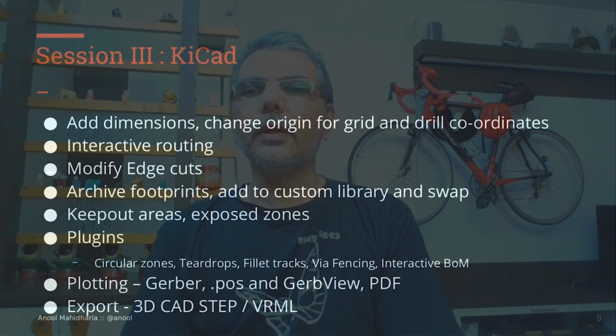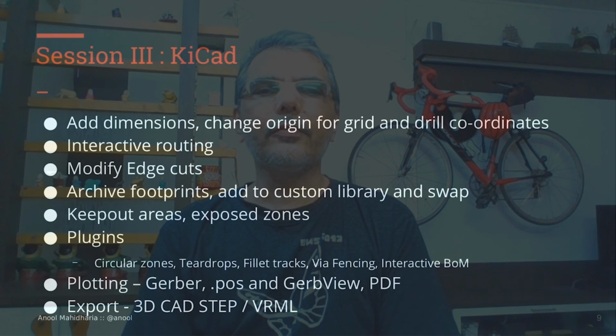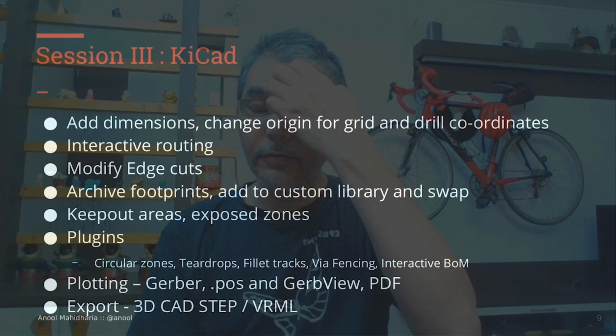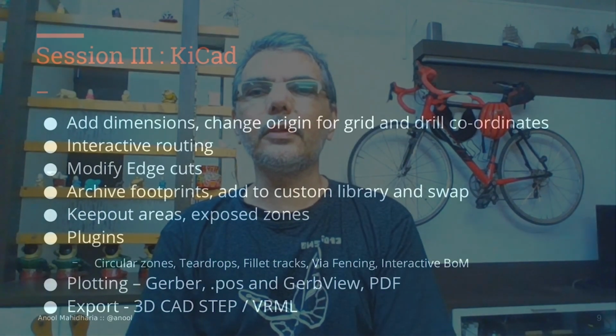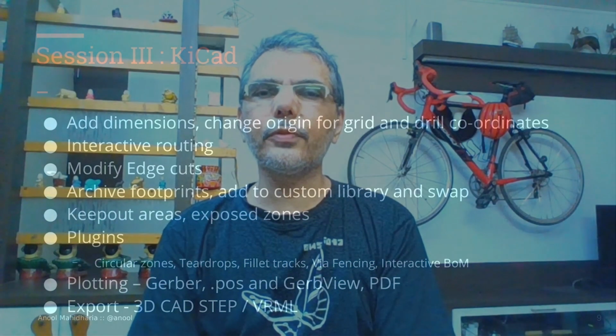We'll also look at how we can produce PDF files equivalent to all of the Gerber layers that we have created, so we can have a visual examination, or someone who doesn't have KiCad can check out the different layers. And finally, we'll look at how we can export the PCB into a CAD format in preparation for next week's session on FreeCAD. So that's the plan for today, and if there's additional time left, we'll cover a couple of other topics like advanced interactive routing or how to create a footprint from scratch, for example. So with that, let's get started.